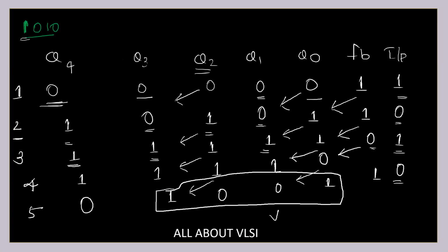Now, that's the reason this particular method we are not going to follow for actual CRC calculation, because in CRC 32 we are going to have a 32-bit polynomial. That means we are going to have 32-bit registers. So in that case, we are going to use another trick, and using that trick only we are going to develop our Verilog coding. This is just for basic understanding of how CRC works.